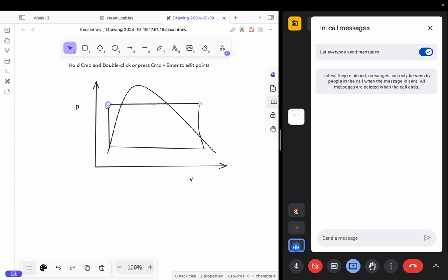So this is that extra thing that you told, that from 4 to 5 we were speaking of before, right? So this curve will be actually a little different. I can't adjust this here, but this is an isentropic process line. This and this are isentropic processes. This is your turbine inlet. This is condenser inlet. This is the pump inlet. This is that 4 and this is that 5. So 4 to 5 is a constant pressure heat addition from subcooled liquid to saturated liquid. 5 to 1 is another constant pressure heat addition, till you reach your saturated vapor, sorry, superheated state or saturated vapor state, wherever you end it.